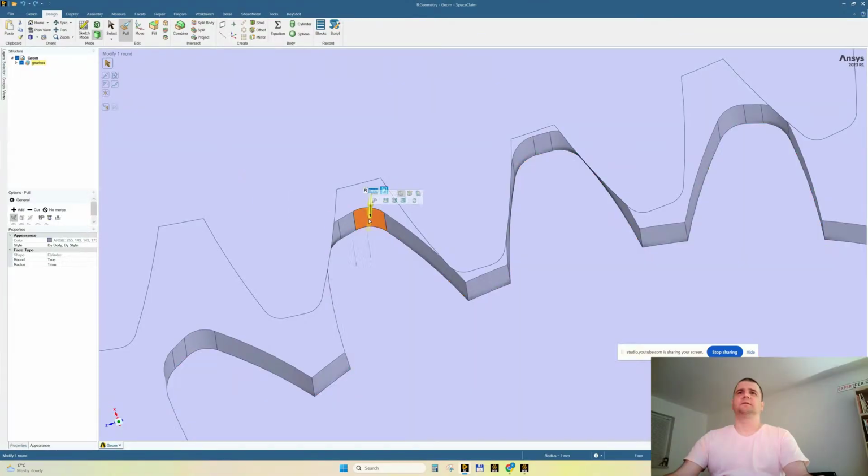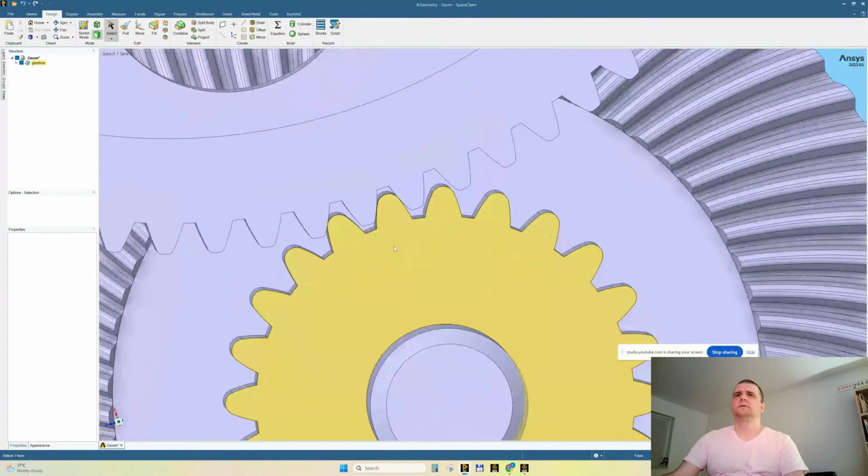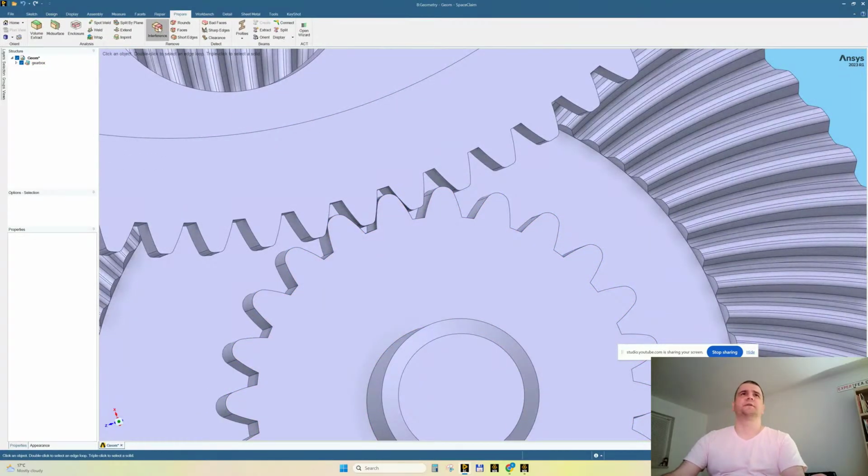Selection. All rounds. Let's make them 1.5 from the keyboard. I'm curious how they join here, the fillets. You know what? For the sake of this FEA, let's leave it like this. And check again for interference. There are no interfering bodies, yes? So we can close this.